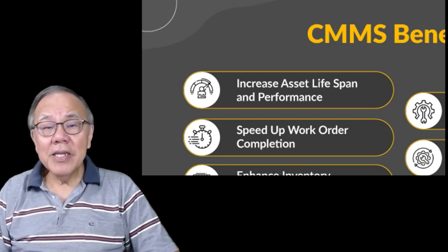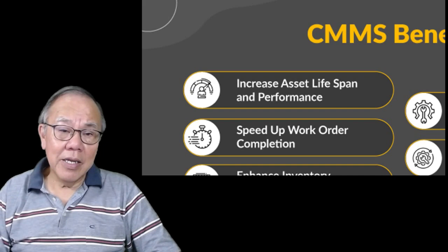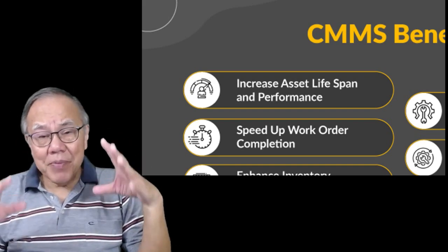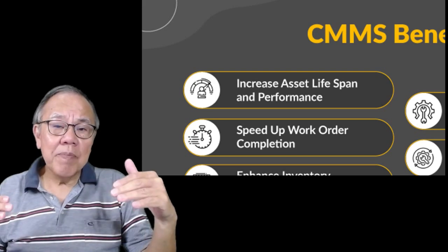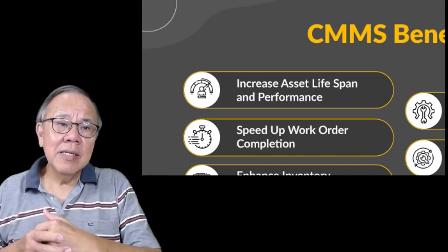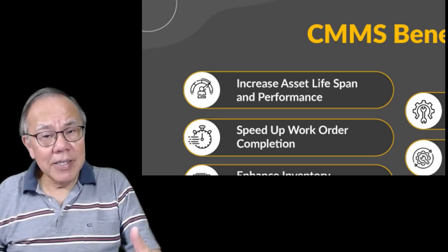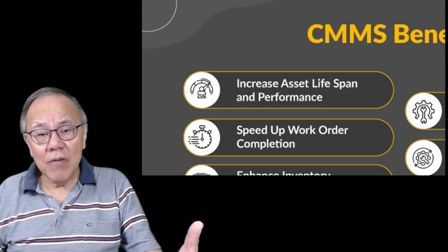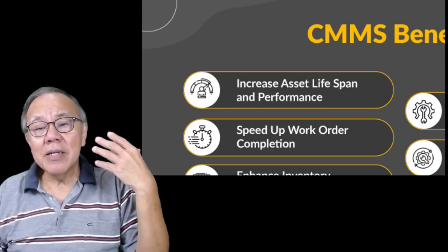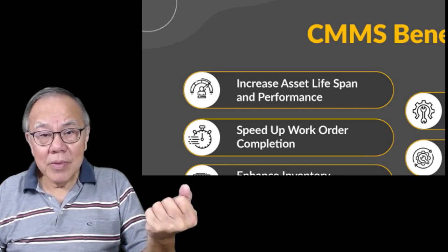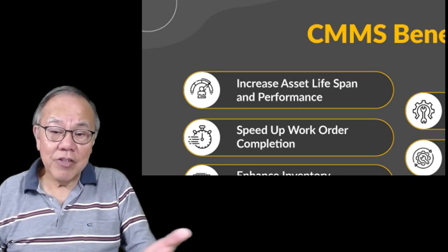And if next month there's a lot of firefighting again, you leave it undone. So CMMS is a very disciplined way of doing your plant maintenance. You can highlight things that are not done, so that people can track. So you have a supervisor on top of you. He should expect you to give a report on what has been done and what has not been done.